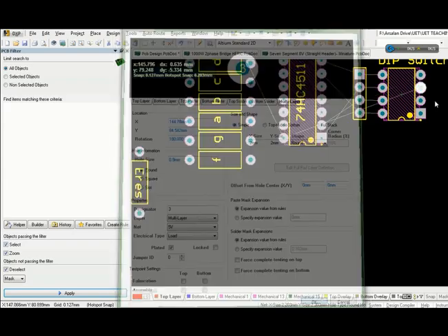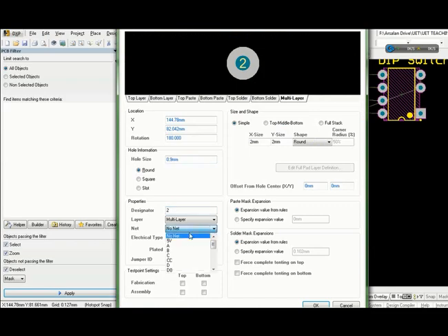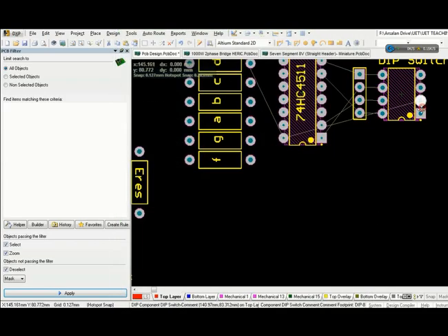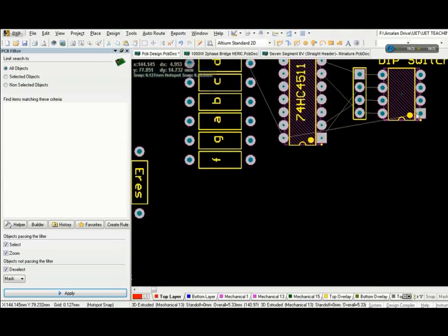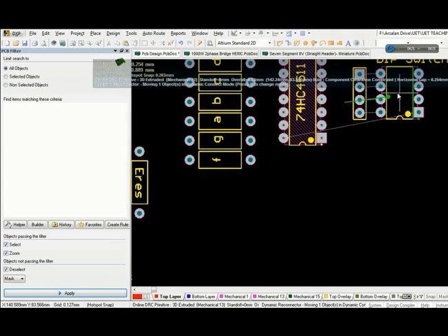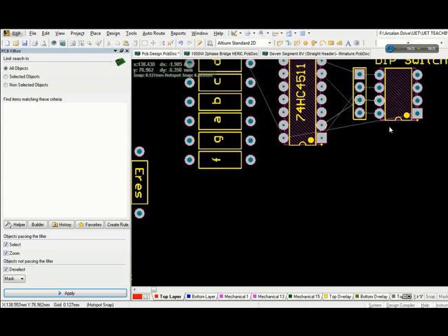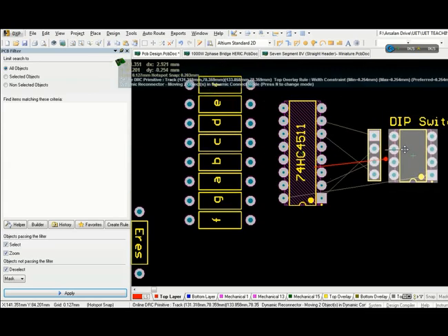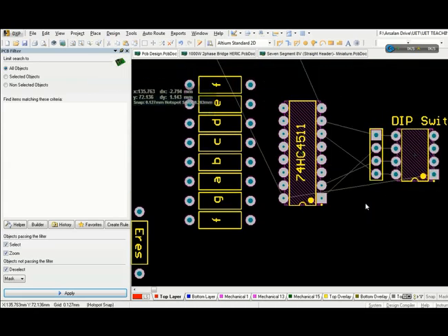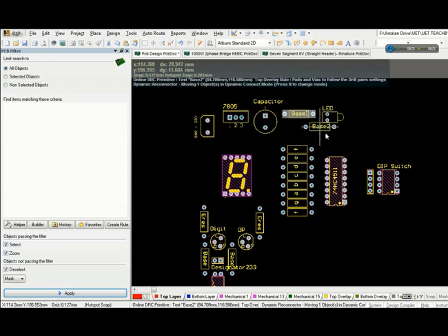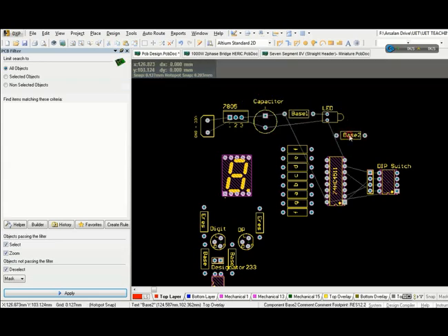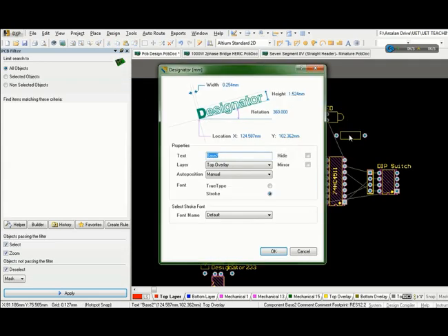One thing very important, when you are going to auto route this PCB afterwards, when all the connections are done, you are again going to do it single layer, but when you are going to route it, there are going to be contentions, so be ready for contentions which you have to actually remove yourself. Okay, so this is all. I guess I could not go beyond this point. This was all the resistance or whatever over here.